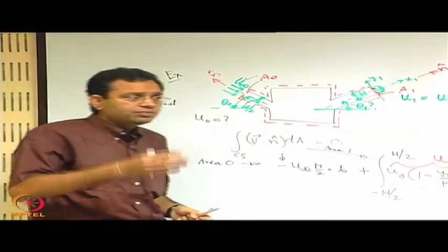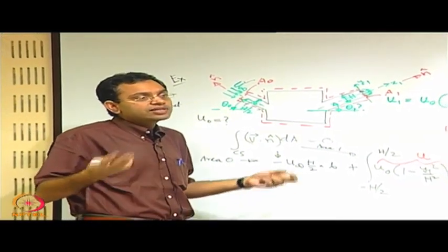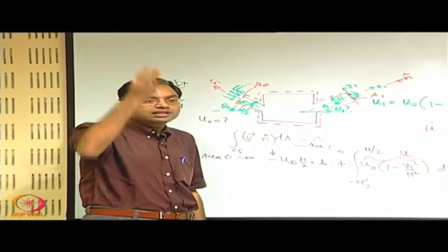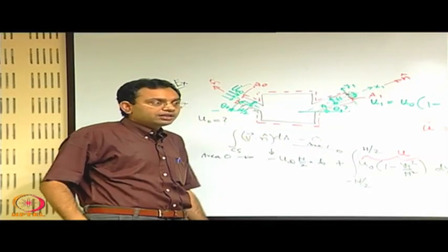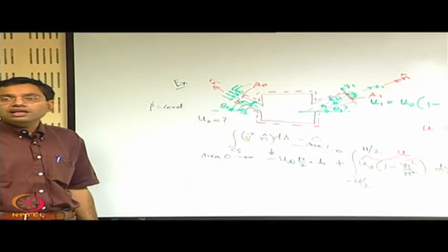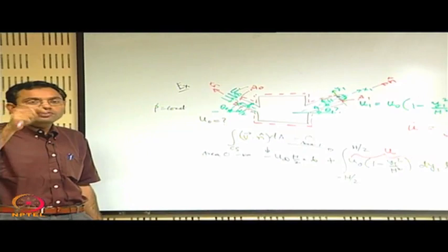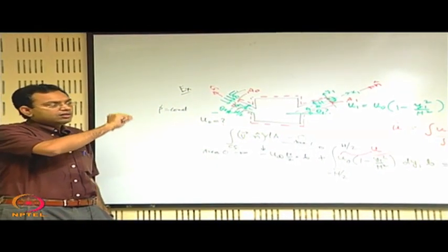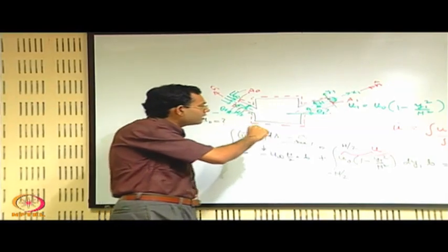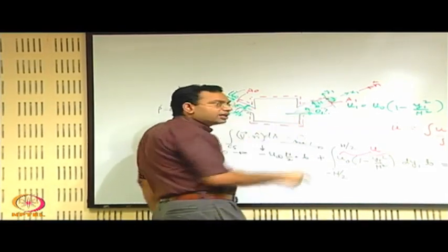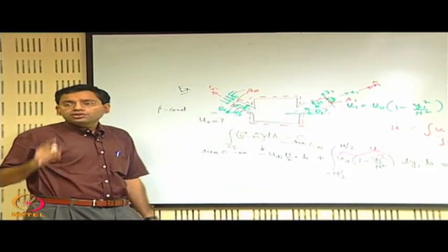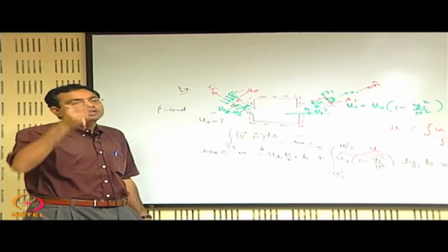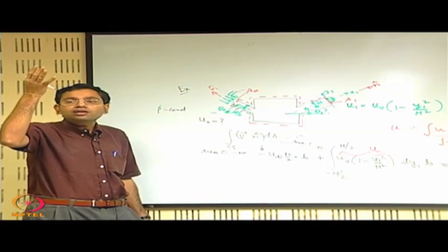When it is uniform it does not matter, it is as good as writing for a point, because velocity does not vary from one point to the other, but you do not have anything called an area at a point. So, when you write a1, in the context of what we have written earlier for 2 points, when we used the Bernoulli's equation, we should keep in mind that there also a1 was for the section that contained the point 1.